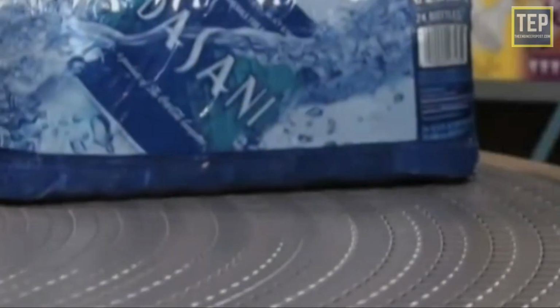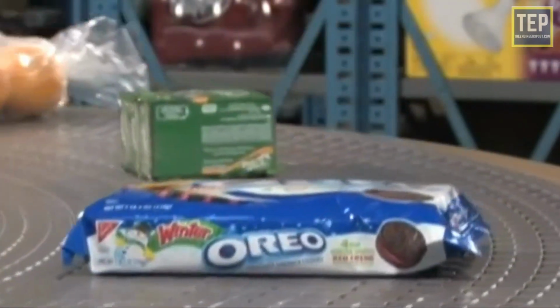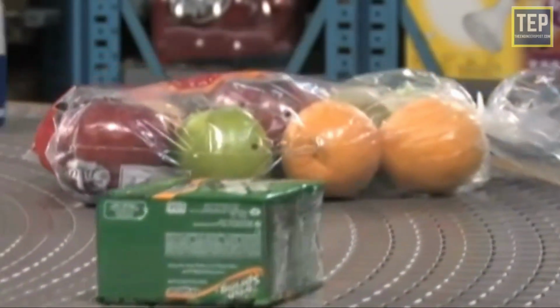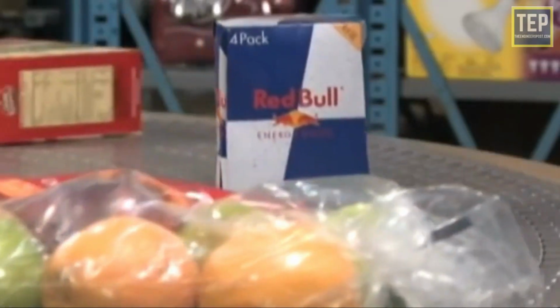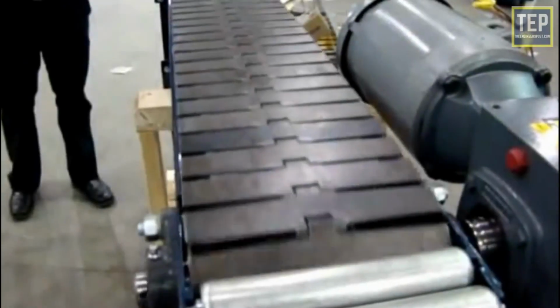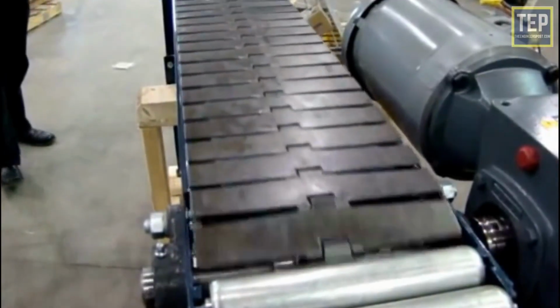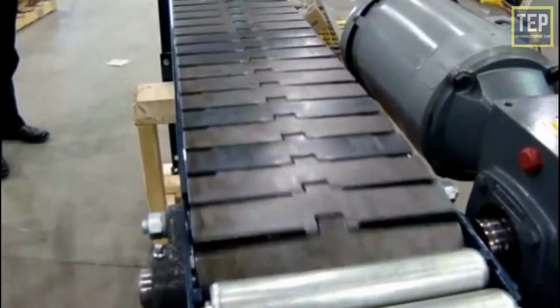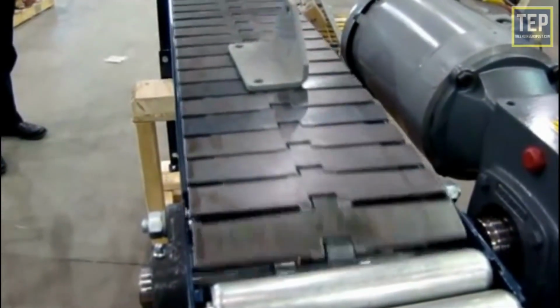Flat-top chains are widely used on conveyors, most basically on the special type of slat conveyor. The flat-top chain consists of a series of steel top plates, with hinge-like barrels curled on each side. Pins are inserted through the barrels to make a joint. The flat-top chain is intended only for conveying.